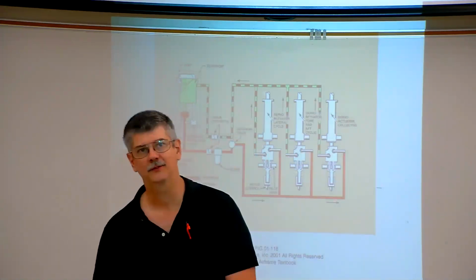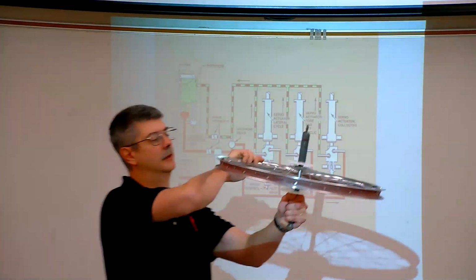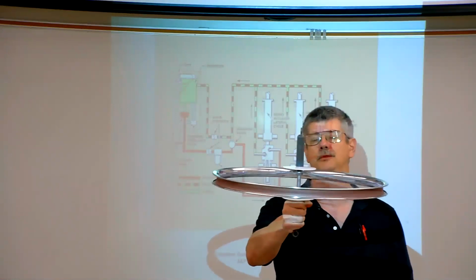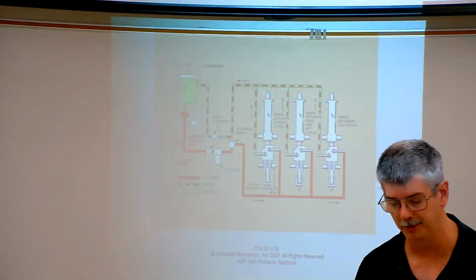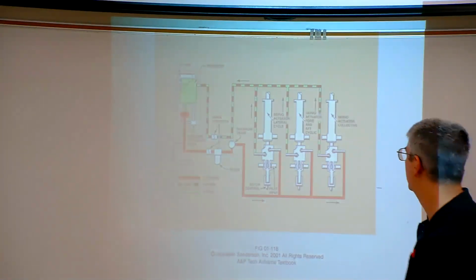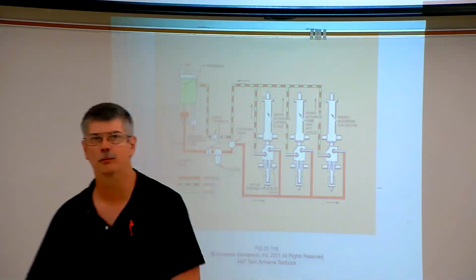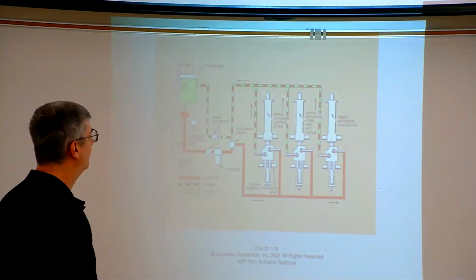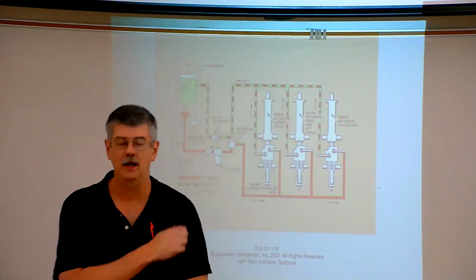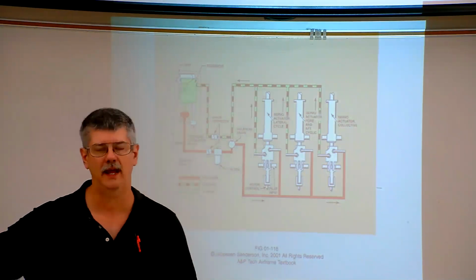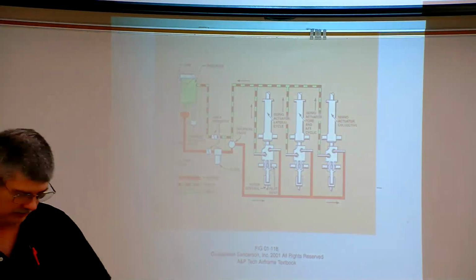But as the aircraft gets bigger, rigidity in space takes over, yeah, and that rotating disc doesn't want to move. So you try to move it, it resists that. So they give boosted, meaning that they will then have hydraulic cylinders to be able to move the swash plate in accordance with what the pilot wants. It's also designed so that the force can't go back to the pilot. The actuators just move the swash plate, and we are good. All right, there's nothing really critical there.